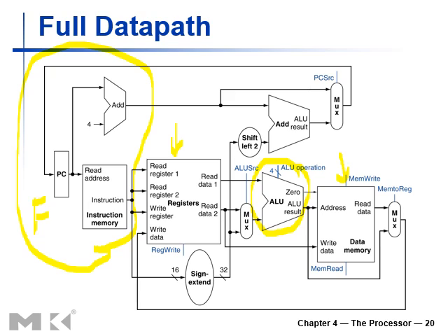So if you see, this particular operation basically controls the branch address. We're going to see that later on. We're going to modify that with the help of this zero flag and some dedicated control signal in order to update the branch address back to the program counter. In this particular diagram, the control unit is not shown, which we will discuss later on.